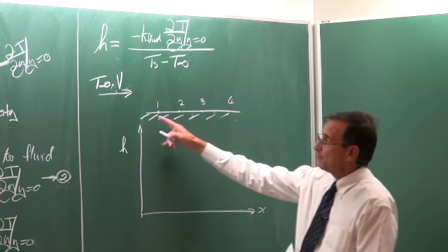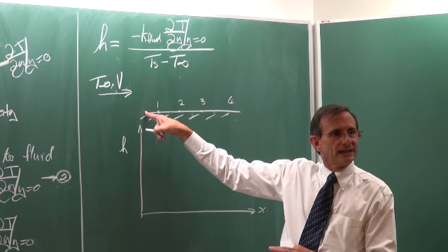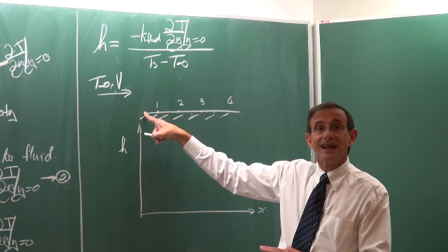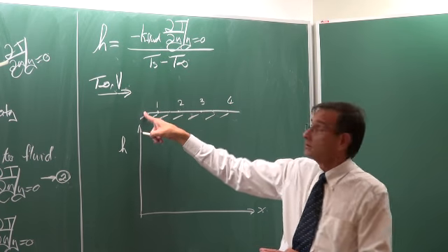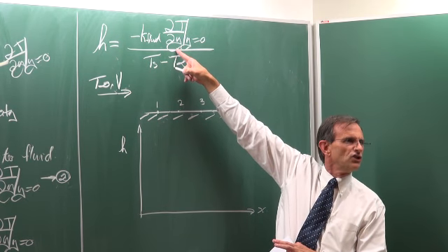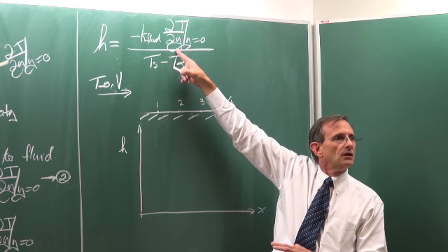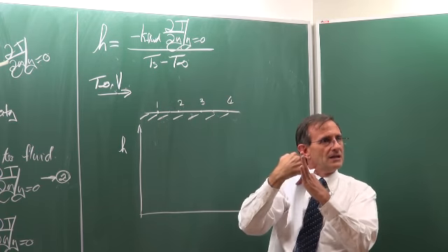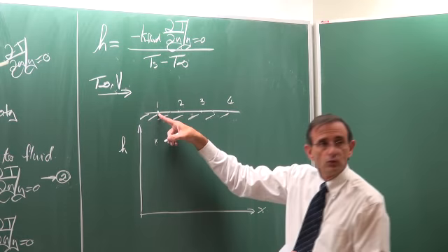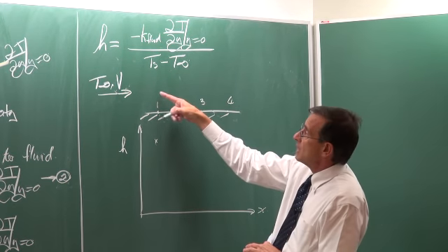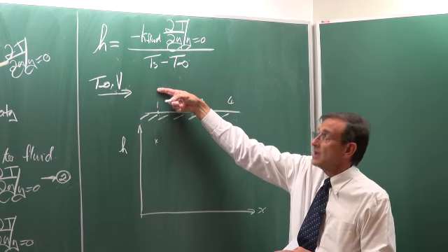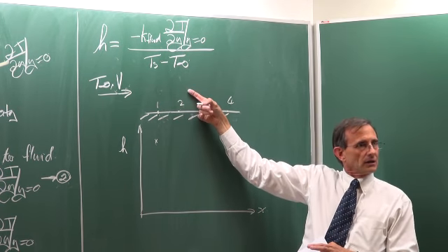Well, what is going to happen is that at the leading edge of the plate, the temperature gradient is going to be the largest. dT/dy is going to be the largest there. Do you agree? The largest gradient is going to be at the leading edge, so the heat transfer coefficient there is going to be quite high. But now remember, heat is being transferred to the fluid. So what happens to its temperature?